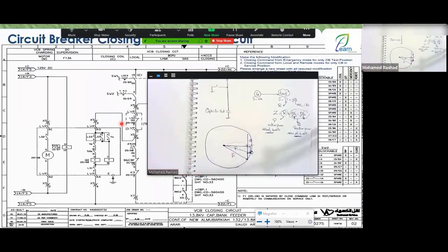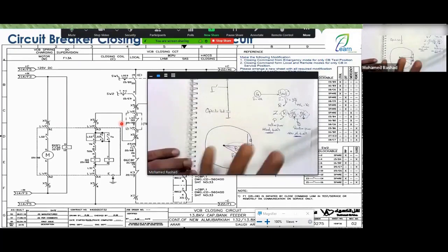This P is what I want. This is what I will provide to the consumer. This is what everyone wants for lighting, motors, air conditioners. Any loads running at your place need P. This is what's important to me. This is what I will charge for. This is my power. You might say, but engineer, you can also charge me for Q.